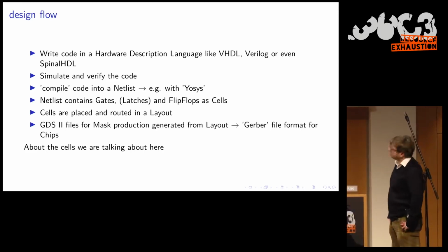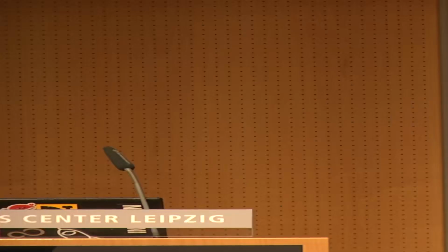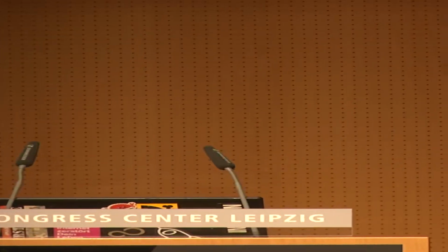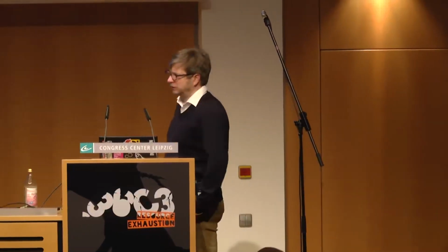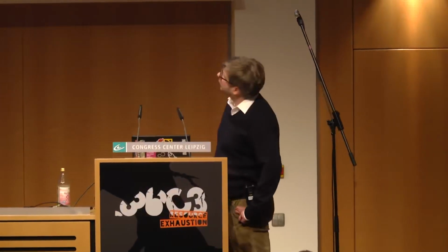And then you try to synthesize it, which is a kind of compiling. We have the Yosys tool, which can do this. It understands ASICs, but also FPGAs. After compiling or synthesizing it, you get something called a netlist.